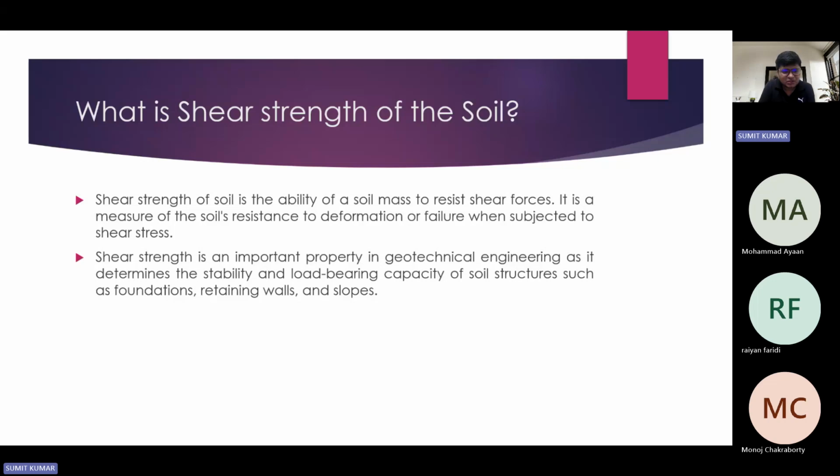So let's start with the very basic concepts again, with the definition over here. The basic definition says that the shear strength of soil is the ability of soil mass to resist shear forces. It is the measure of soil resistance to deformation or failure when subjected to shear stress. Shear strength is an important property in geotechnical engineering, as it determines the stability and the load bearing capacity of soil structures such as foundations, retaining walls, and slopes. This is also mentioned in the earlier slides which we were discussing earlier.